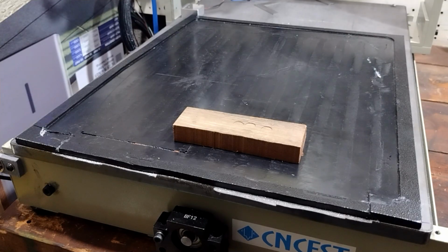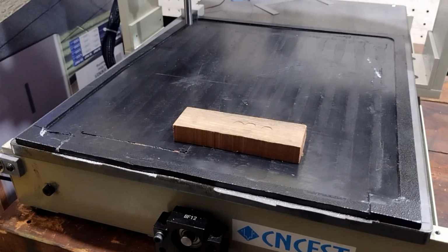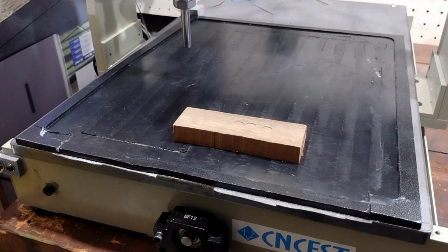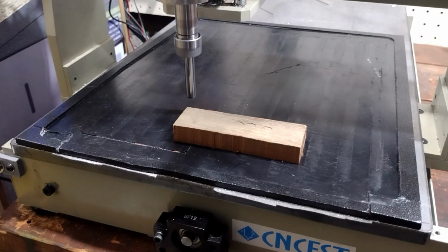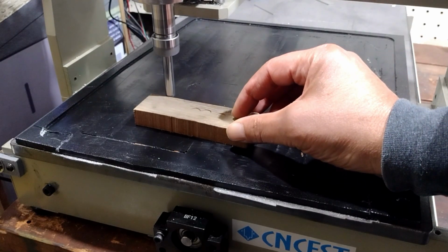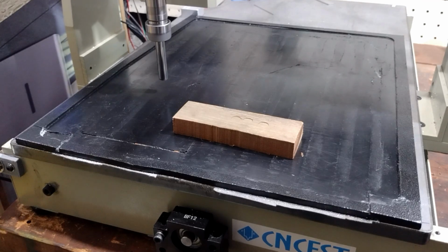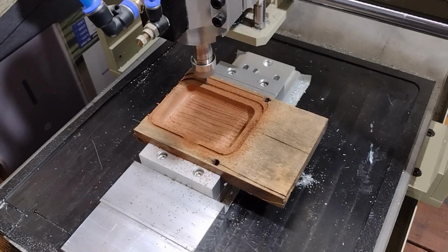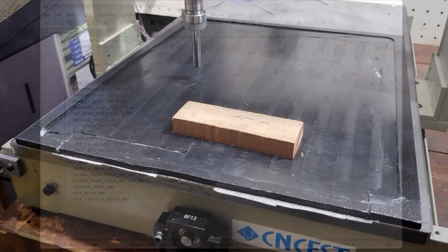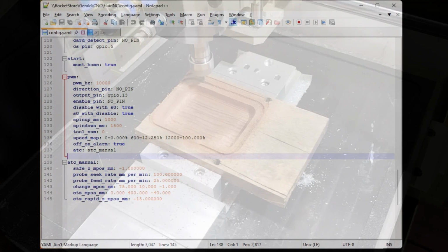When the job continues, tool 2 should begin to cut 1 millimeter below the top surface of the workpiece, which I will slide into position to demonstrate. One millimeter. P.S. When the job ends or aborts, the Z0 reverts to its position with tool 1.